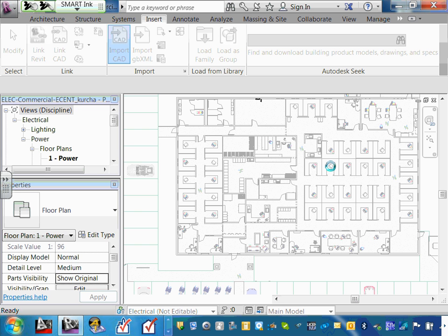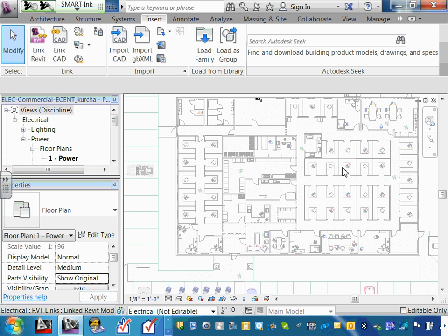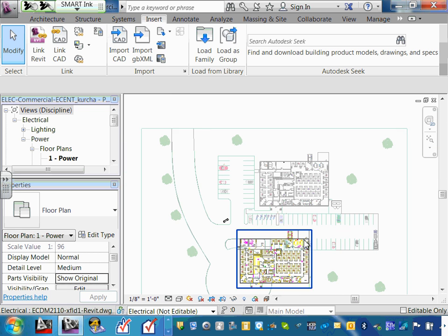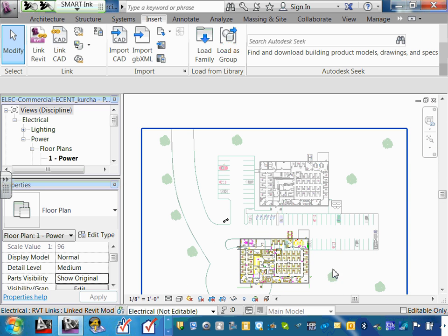So, importing a CAD file into Revit. Now remember, a CAD file is 2D. It's going to come into the 3D. It might be offsetted. If it's offsetted, we have to move it. I'll show you. Okay, gentlemen, here's where it dropped. Can you see where it dropped?